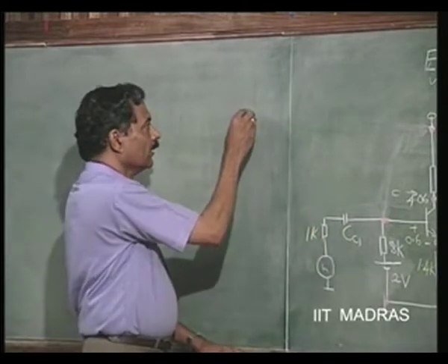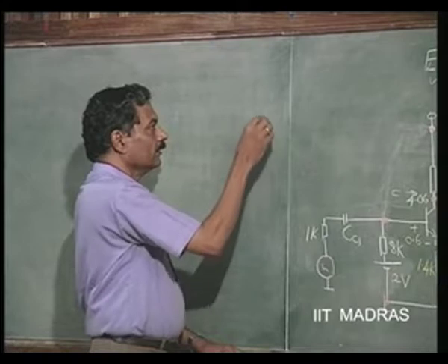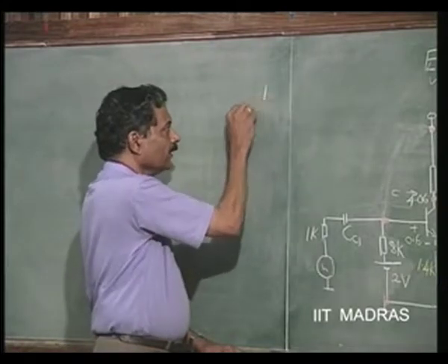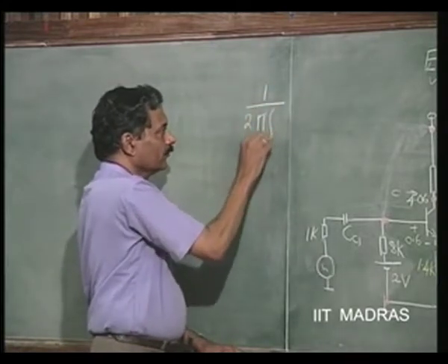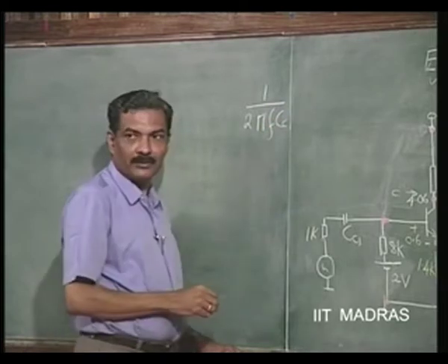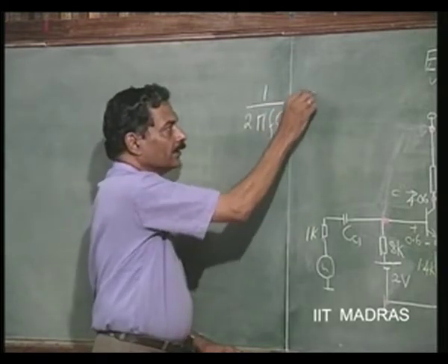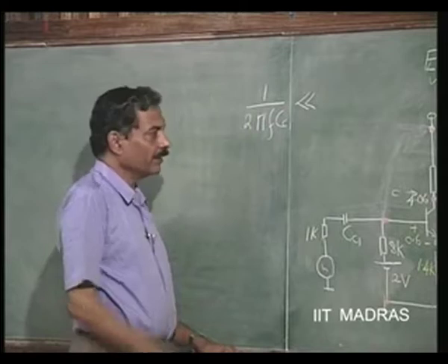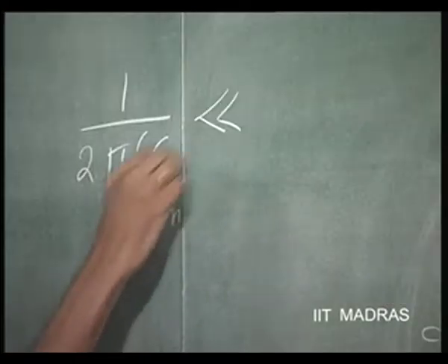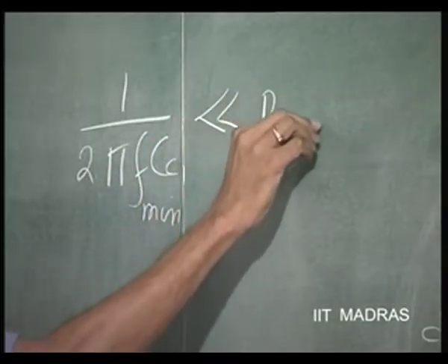Now, I just said that the reactance of all these capacitors should be much less than the resistance across, at the minimum frequency of interest.